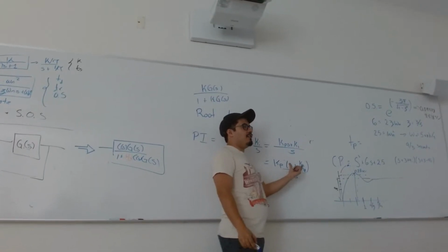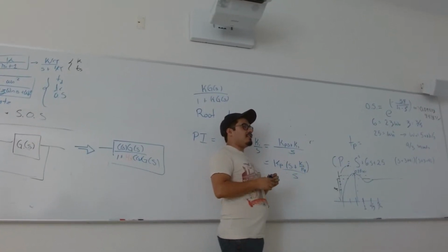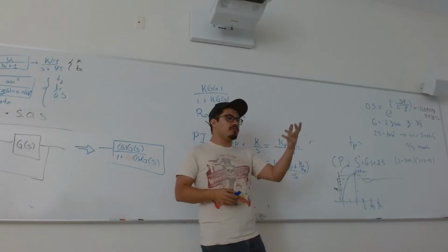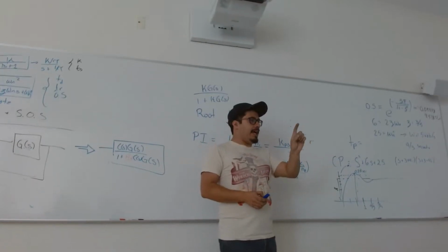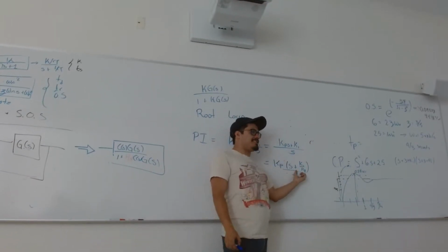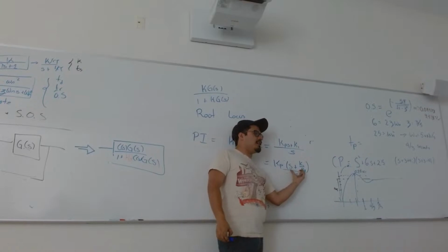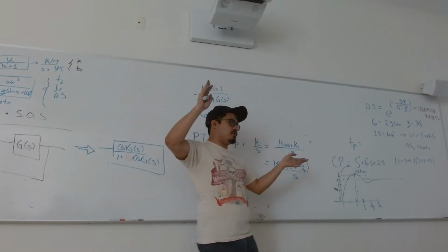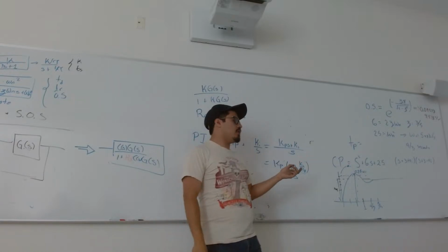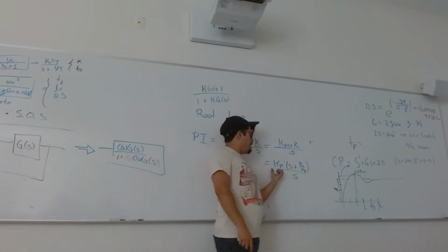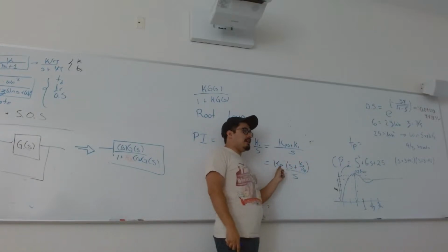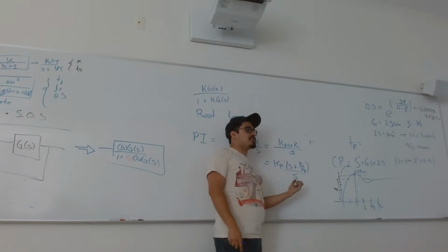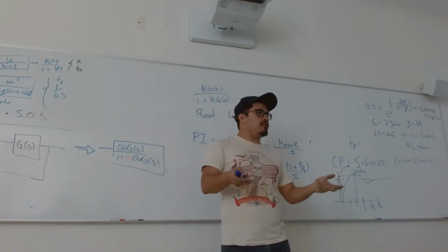When you use Control System Designer, you add a zero, and you can move the location of that zero. That is moving this part, and then moving how far along the branches of the root locus you are going. So once again, you keep just moving along the branches using this gain, and these zeros and these poles are changing the shape of the branches of the root locus.